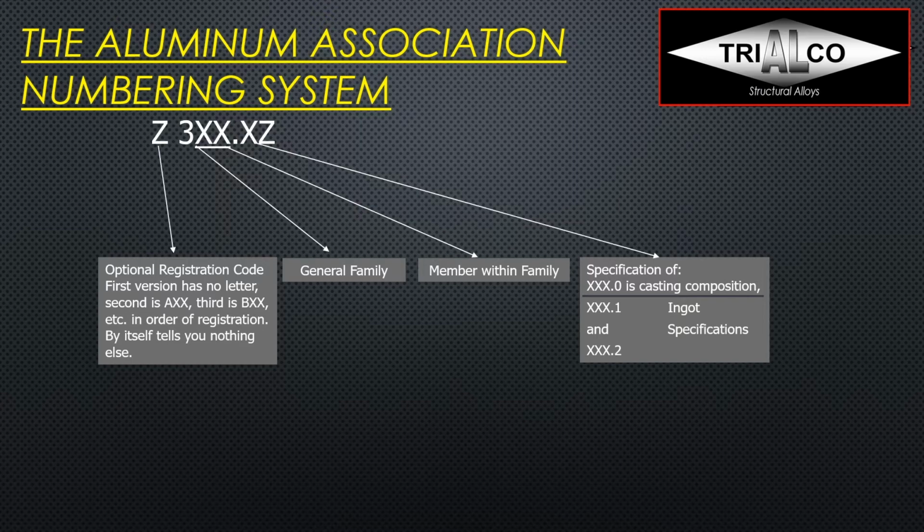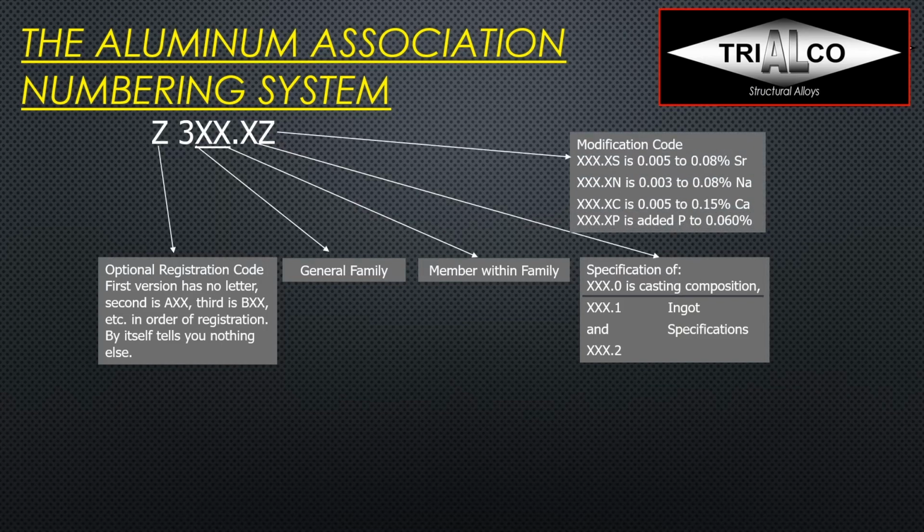So usually you will see slightly higher purity in terms of iron and things like that you will pick up. And usually you will see a little bit higher strontium or magnesium or anything that you burn off. And some foundries will obviously burn off a little more or pick up a little more than others. And therefore we have also a dot 2, and dot 2 is then the higher purity specification.